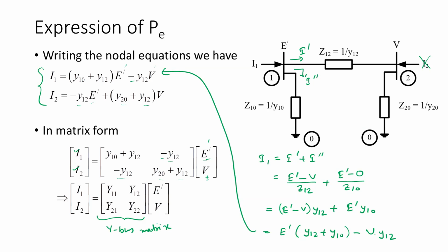I think you had some relationship between the diagonal elements. What is the relationship of the diagonal elements? How did you develop the diagonal elements for a Y bus matrix? Let's see how much you remember. Summation of all the admittances connected to a particular node or bus. Yes, same thing. So it is the Y bus entry for all the admittances connected to that single node. So your Y11 is essentially the sum of all the admittances which are connected to your node number 1.